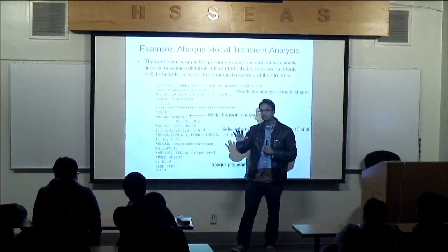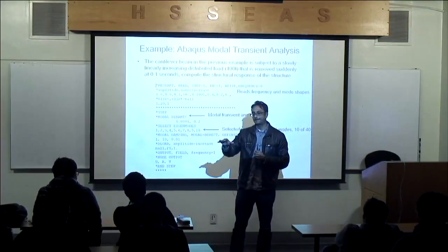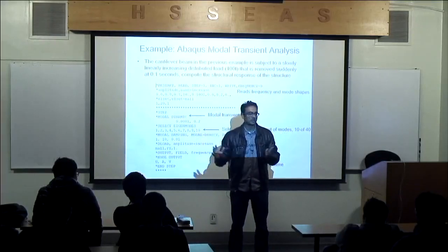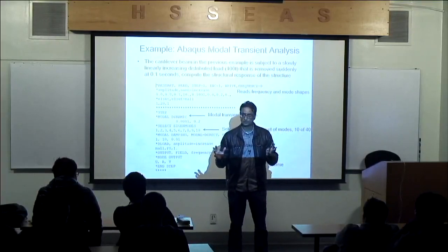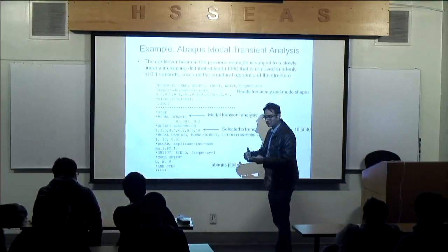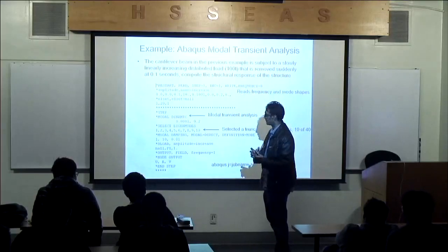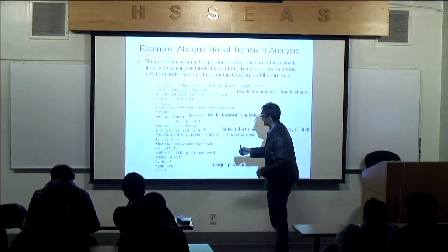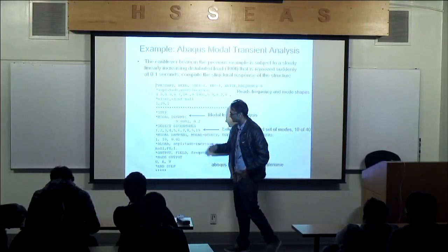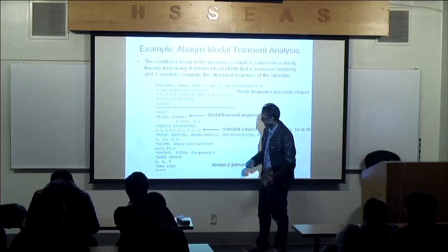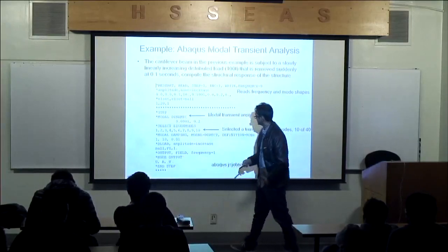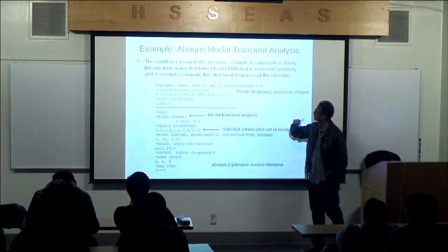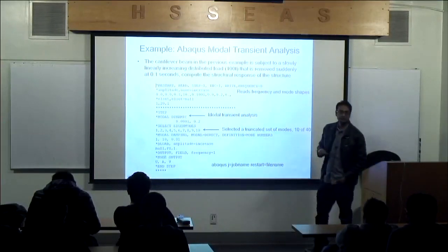Because, you know, I truly don't believe that this beam is going to deform with all those waves in dramatic fashion. I really don't think that's going to happen, because I feel the frequency content of the problem that we're looking at is really not like this, okay? I put modal damping of 1%, and I just wanted to know the accelerations and velocities. So you guys can see here, I select a truncated set. That's what initiates the modal dynamic. I'm getting the DNA of the system.